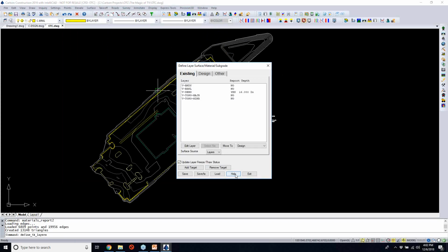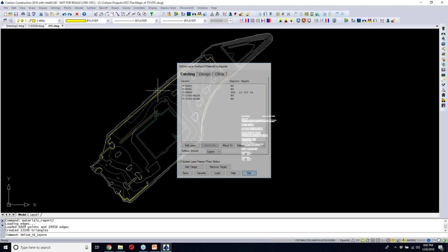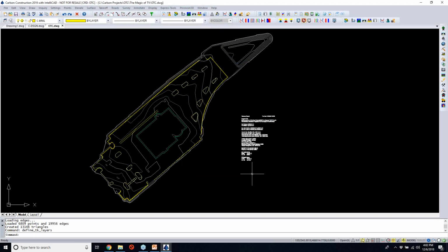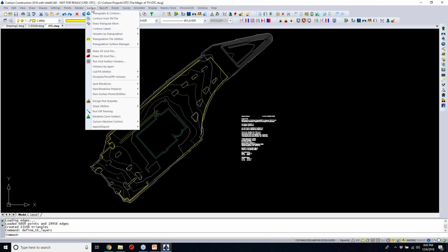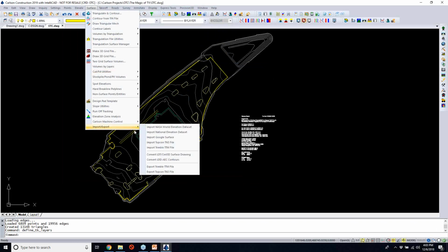The last thing I want to talk about briefly in here is a question that came up to me earlier today with a client that called in, sort of in response to all this, was outputting all the models then out to machine control. So as we are producing these different surface models, these are being exported out to a Carlson TIN file format. It's very easy then to take the different surface models.